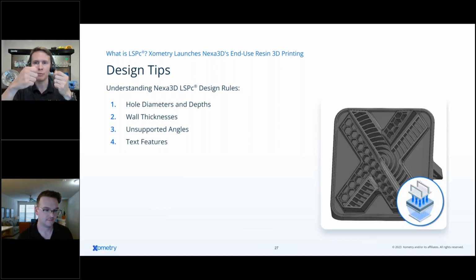Everything we're thinking about is, will it grow, and will that feature need supporting structure? Will the supporting structure battle the feature? I don't want the supporting structure to win. I want the part to win when I'm snapping off the supports, right? So thin walls, thin geometries, and also things like, will it create suction or vacuum as it's building? For example, an upside down cup.